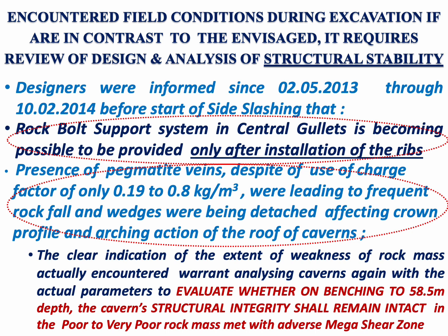So it was necessary to evaluate the structural integrity of the cavern when it would be excavated to its full height, whether it would remain intact or not when the rock condition is poor to very poor rock mass and is intersected by an adversely oriented, deep and sharply dipping mega shear zone.